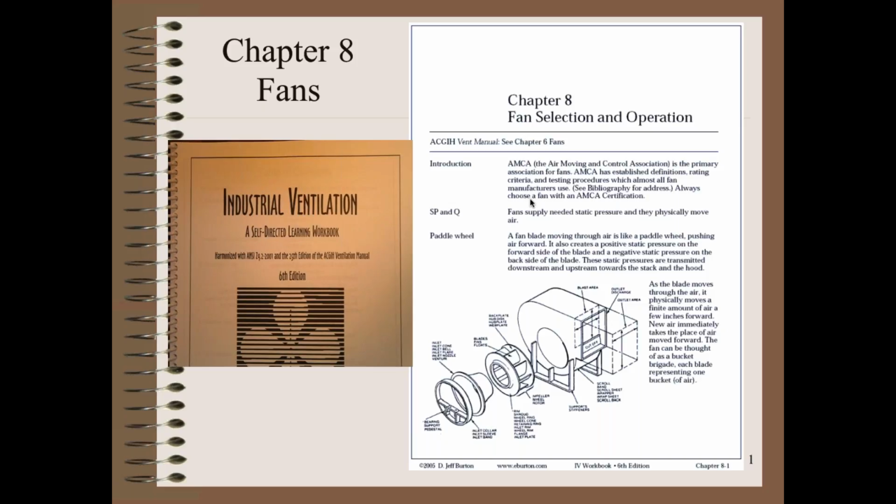So you come out of here, you might have to go straight and then turn and go up through, if this is inside the plant, which is not that unusual because you want to protect it from the weather sometimes. So you go out, you turn, go up. So now you have an impediment, an energy loss that wasn't there before. So just like you designed the suction side, now you design the discharge side.